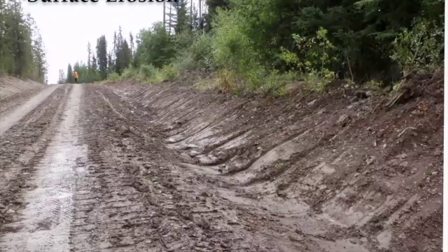When you are building a road and you open up bare soil, you are leaving the ground open to erosion. This is most apparent when you are under the construction phase, or in this case, when someone is cleaning a ditch line. It takes some time for the disturbed ground to re-armor and revegetate, and during that period, it's going to erode. Whether that erosion product reaches a creek and becomes sediment or not is a key part of the evaluation.